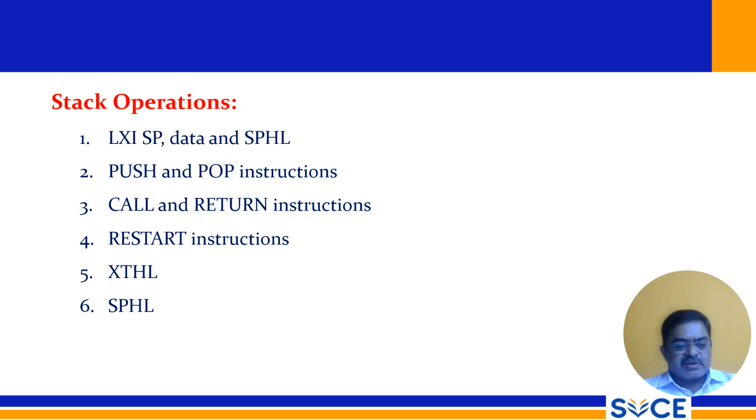And the stack operations. These are special purpose operations: LXI SP data and SPHL. Here we have push and pop instructions, call and return instructions, restart instructions, and the XTHL and SPHL instructions.